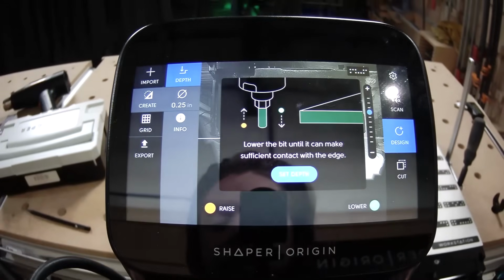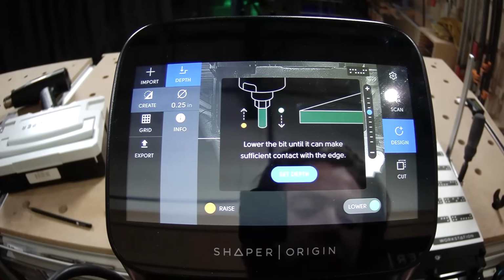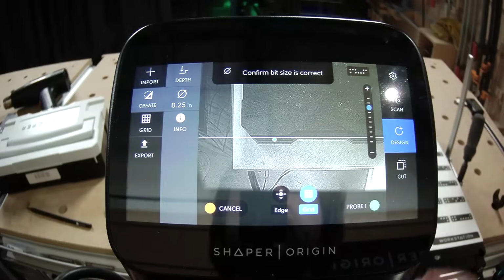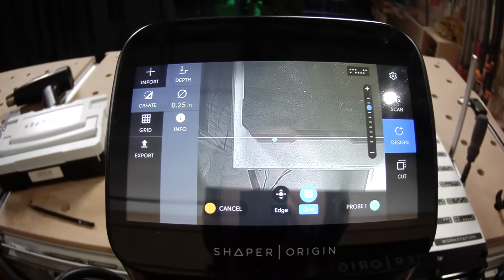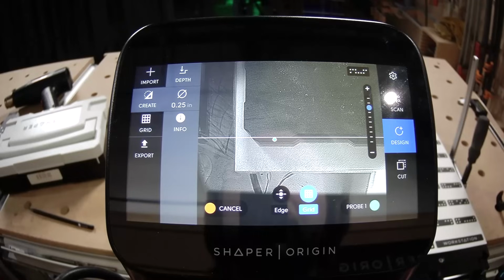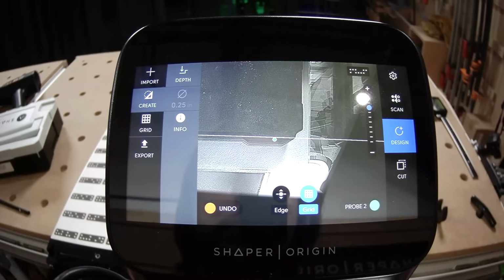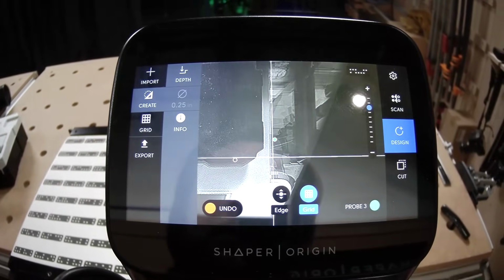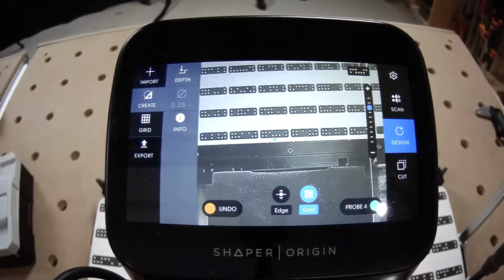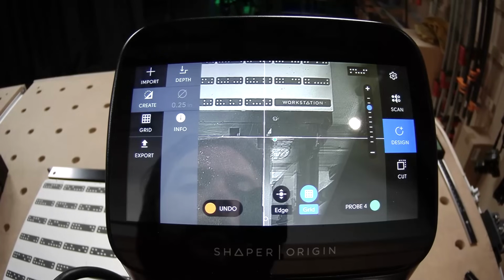Yeah, that makes sense. We've got to design some shapes so that we can cut out the shapes for this ruler first, is the first thing that we're going to do. And we want to make sure that that's aligned to the foam. This rectangle probe is a great way to get that alignment, get the XY alignment, make sure that everything is square, and also get our center point, because later we're going to export this design, this workspace, to Studio and add some tools in Studio as well. So getting this rectangle probe is going to give us the center of this kind of funny shape, and give us the alignment that we need to make sure that everything's nice and square in our toolbox.